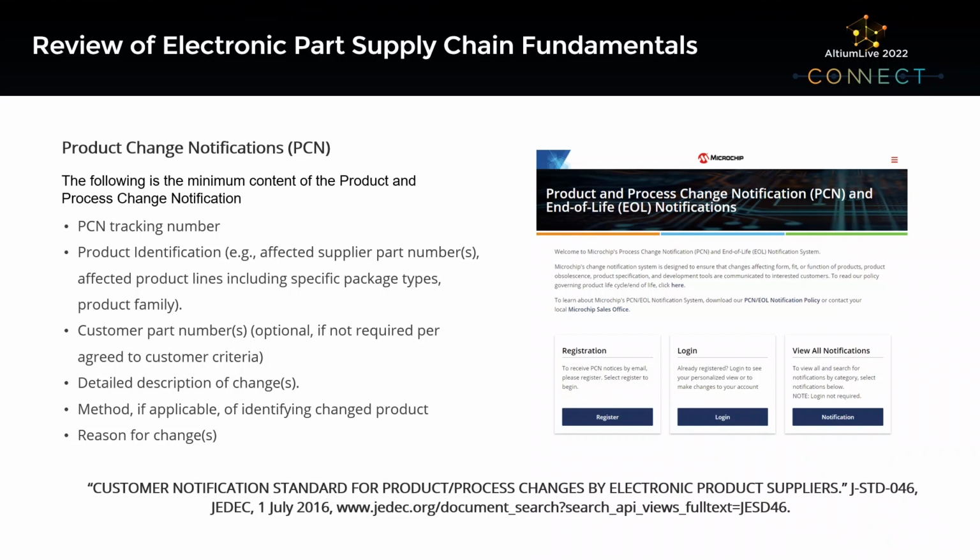There's a JEDEC standard, JESD46, if you're so compelled to research that further. And there are minimum contents of these product change notifications: tracking number, the product identified, detailed description of changes, etc., as you see on the slide here.